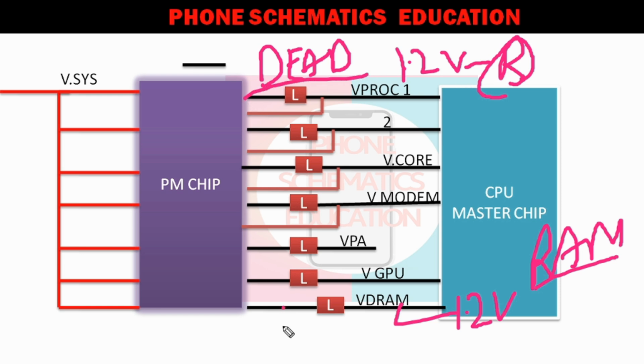You can check on the capacitors in this line, right? This line is also connected to the CPU. If any connectivity is lost with the CPU, power IC and the RAM through this line, it puts your phone in a dead condition. Now, let's get back to the schematics again and let's see the remaining lines. For this, get back to the schematics.